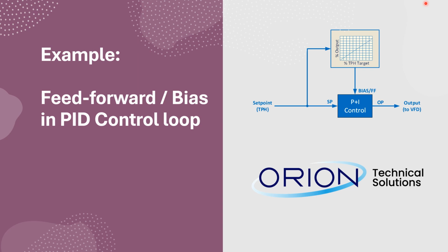One of many powerful functions that can be helpful in many of these situations is using feedforward to bias the controller output. This feature has been available in nearly any controller produced since the 50s or earlier. I'm going to give a simplified real-world example of how this feature can help solve some process control challenges, that will hopefully help you understand how you could apply it in your situations. And hopefully this will help stimulate some ideas and spur interest into some of the other PID functions and features that could and should be helping solve some of the other control issues that you're likely running into.